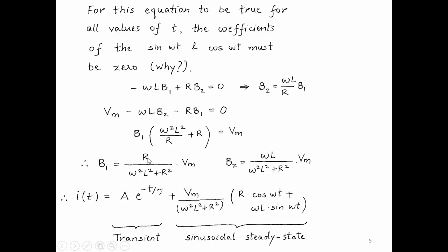Okay, so as I said here, what we found, just to repeat, is that when we open or close a switch, there will be a transient, and the transient will die out. And if the input is sinusoidal, then only the sinusoidal part of the currents and voltages will remain. Now, there is a very large number of circuits and systems where one is interested only in the sinusoidal steady state response. One is really not interested in this transient response.